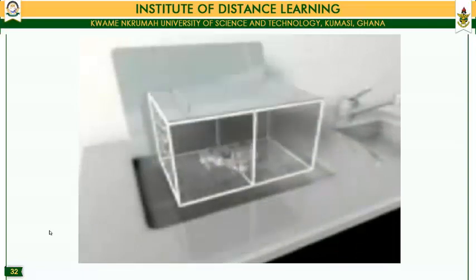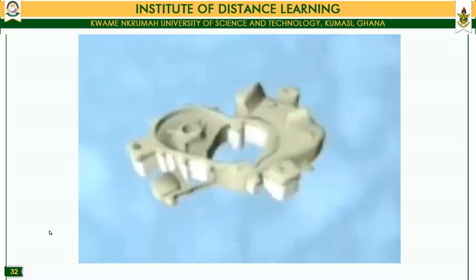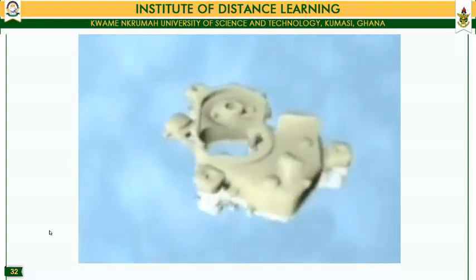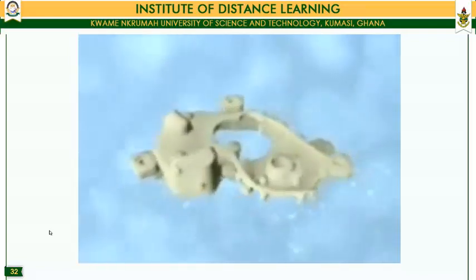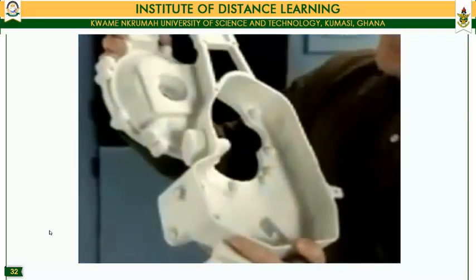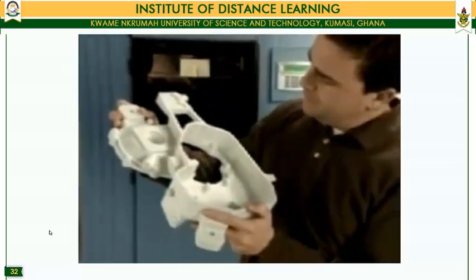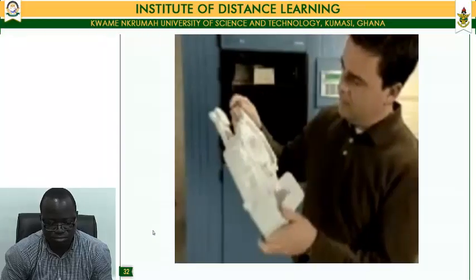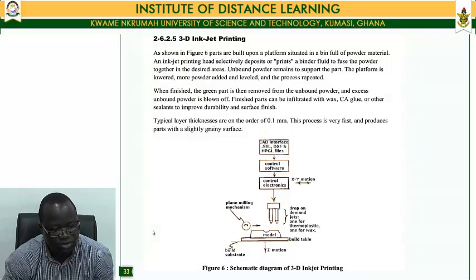When applicable, WaterWorks provides the final step, enabling complex geometries and fully functional assemblies in a single build. Soluble supports are simply dissolved in a water-based solution, resulting in a part with smooth surface finish and fine detail intact. Okay, so that is the fused deposition modeling concept.